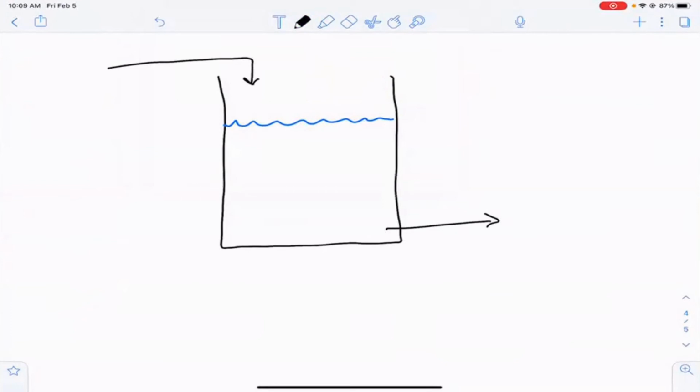The thing about a CSTR is that you're always operating at the most dilute point. So getting to high conversions means getting to the lowest concentration of A or B. In this particular case, you have both of them, right? So how would you do that? It turns out one way is to introduce a recycle stream.